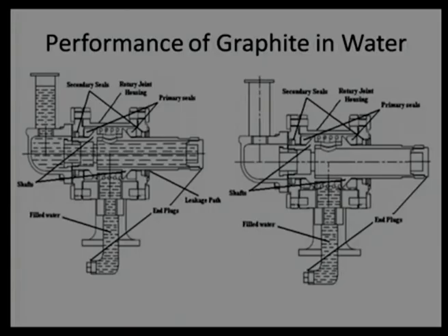So, first the rate of transformation is high, and the deformation or dislodging of that wear transfer layer is high, and because of that there is a high wear rate, as well as a reasonably high coefficient of friction overall.